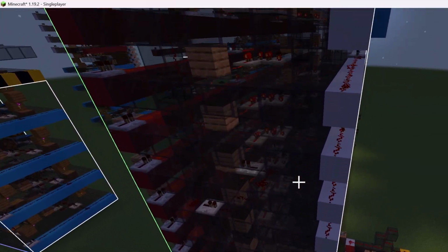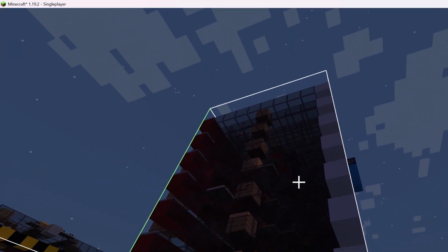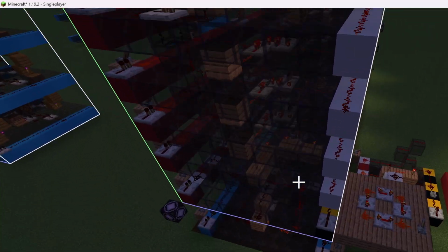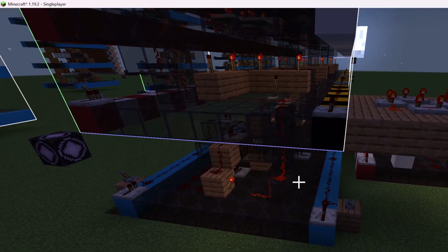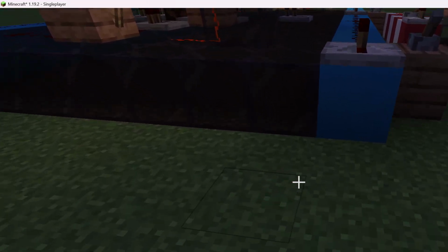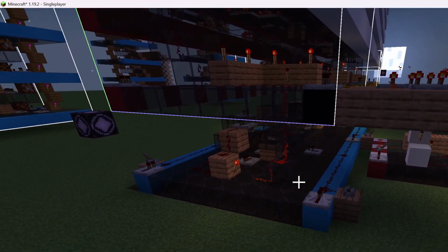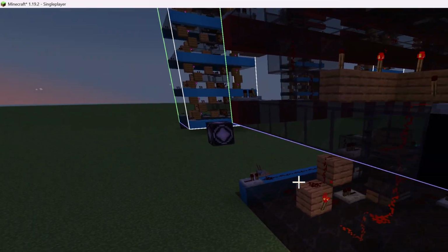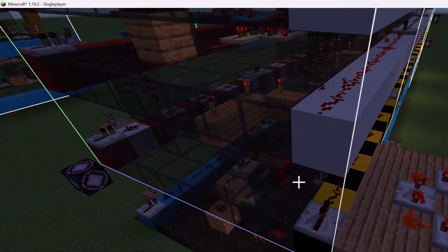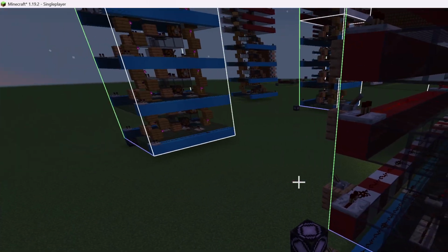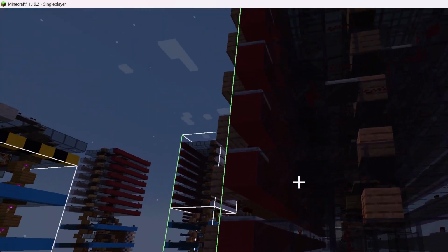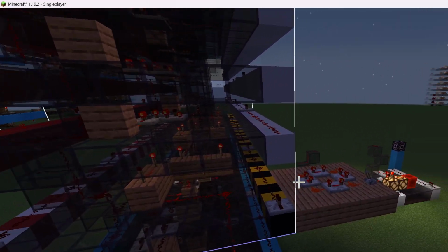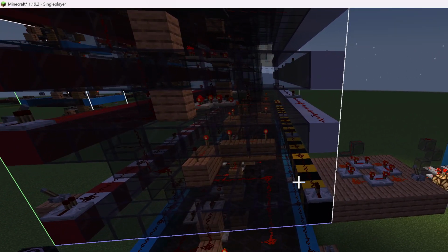But yeah, that's all this passes the data in. So each one of these is a bit, and then you have 8 levels that carries 8 bytes. And right here is the control. Sorry, I'm dropping stuff here. But this is the addressing layer right down here, which tells it which address, and you set the bits on the 2 address lines on either side. And then this is the control layer right here that you send the signals in to commit a write to the cell or to read the output on this end based on the control logic put in here.